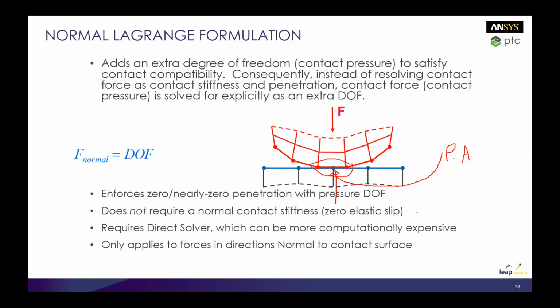The downside with this is it requires the direct solver, and this is more computationally expensive. Okay, so this only applies in the normal direction. In a sliding direction, you've got a similar thing: you have to have a small amount of relative sliding to transmit shear forces.